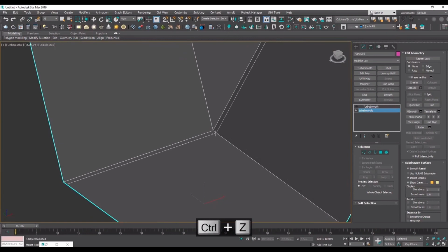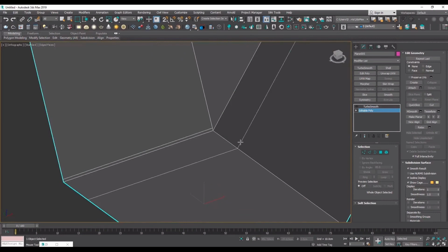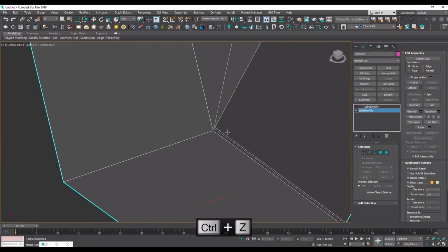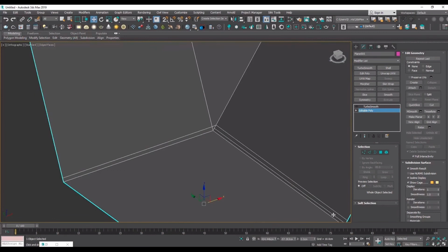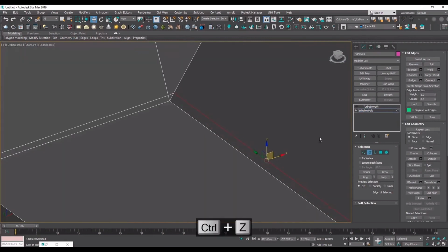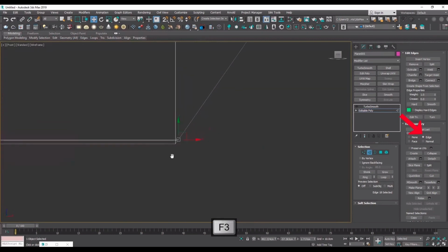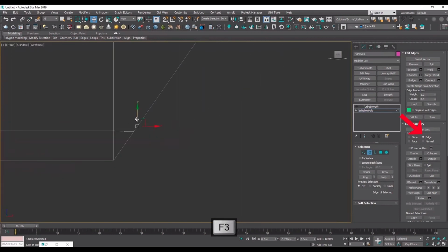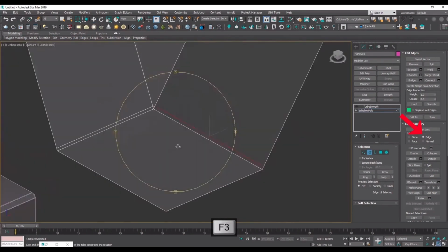Knowing this is very crucial to edge flow and edge direction. I now can create edge on one side, and as you can see, there's no more triangles, so it's going to be normal all over again. So now I want to adjust the angle by doing edge sliding. I'm going to select the loop and go to my side view, put the constraint on edge so that I only move my vertices and my edges on the surface of the edge and not in the air.